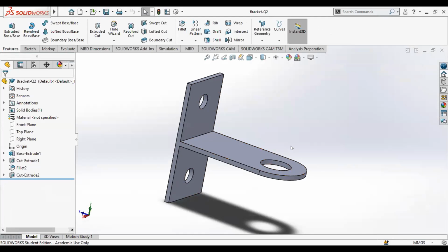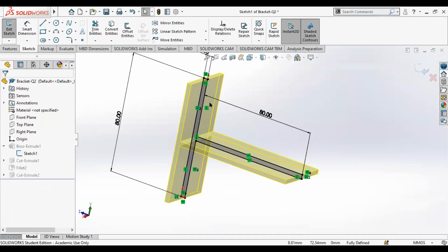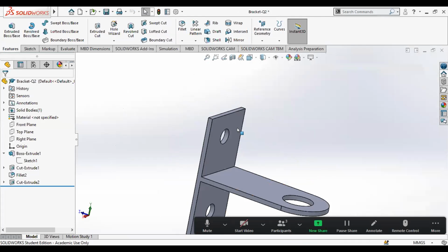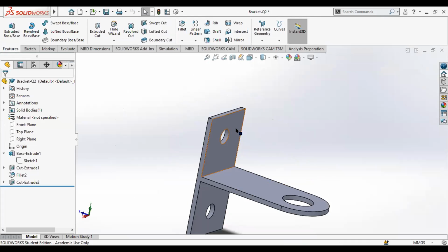Let's say I know it can withstand 10 kg, but maybe it's over designed. Sometimes when we design, like the plate you saw just now, the thickness of my plate is 3 mm. I put 10 kg of load, and the maximum stress from the analysis is 170-something megapascal, but my material can withstand about 300-something megapascal. So it already can withstand 10 kg of load without failure. But maybe I would think it's over designed, because the material can withstand 300 megapascal but the subjected load is around 170. So it won't fail, and maybe I want to save cost and can reduce the thickness.